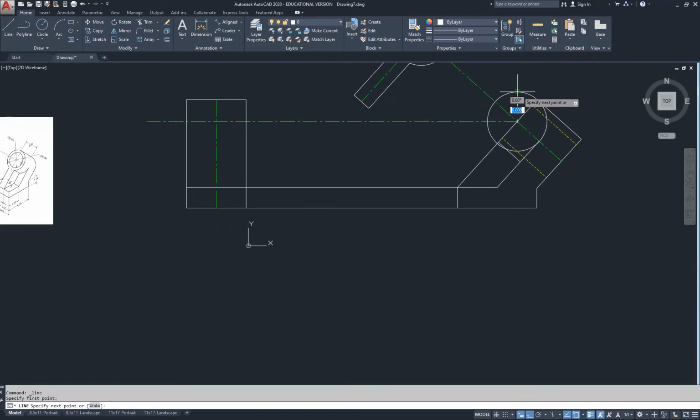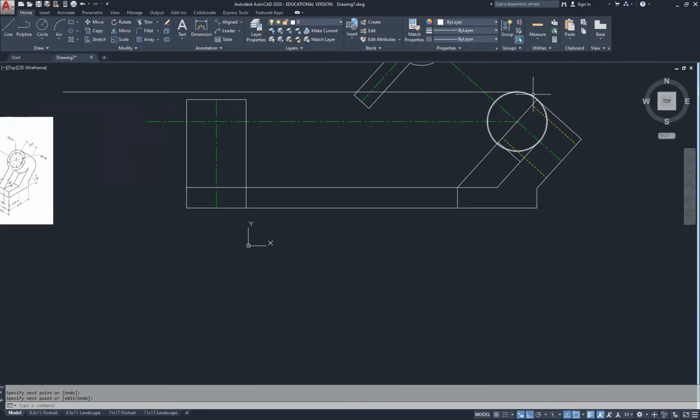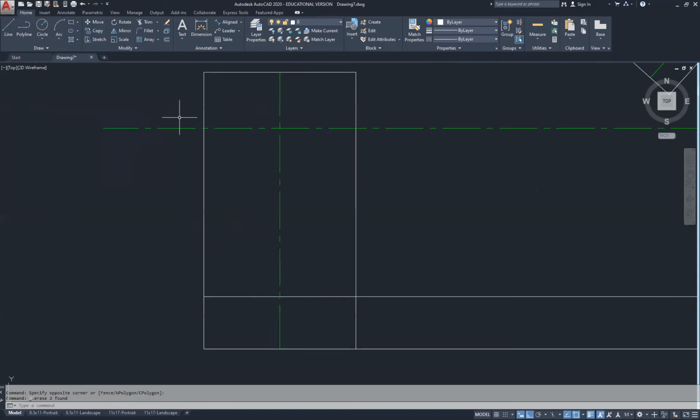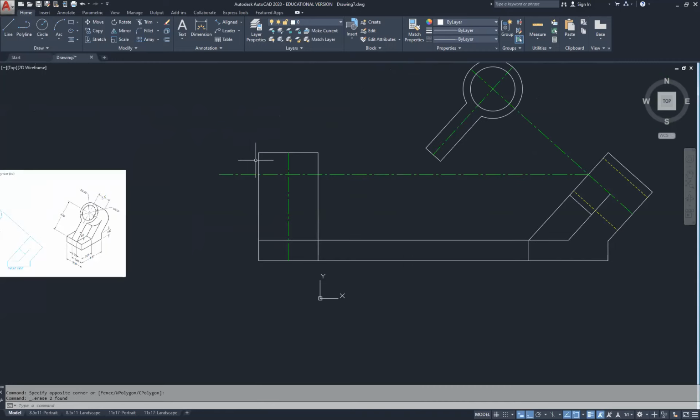The top of the circle is not there. What's happened is that circle has rotated down to this point down here. So the circle looks on this view as a foreshortened view. So in order to represent that here on this face, I'm going to use a command called ellipse. The ellipse tool is right here. And we need to use the axis end command.